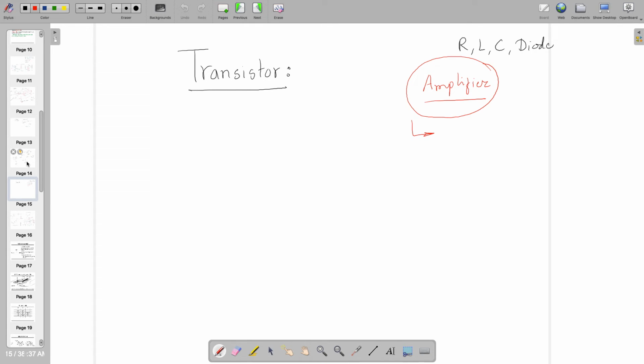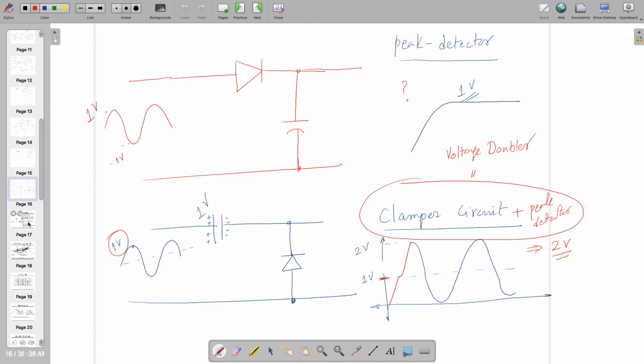So these transistors are weaker. You need the power MOSFETs for that one, which can sustain 100 volts or 150 volts. But what if I want to use the power electronics industry where the voltage is in megavolts, right? You heard about this, right? Megavolts, kilovolts. We don't use transistors over there. We cannot use. So then you have to follow all these techniques, peak detector and voltage doubler.